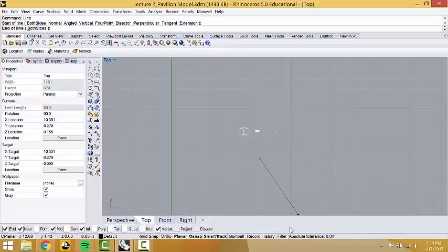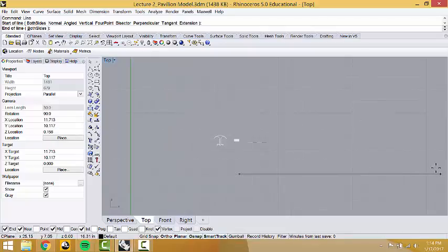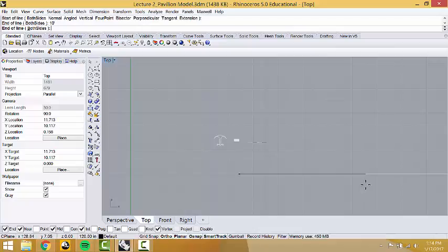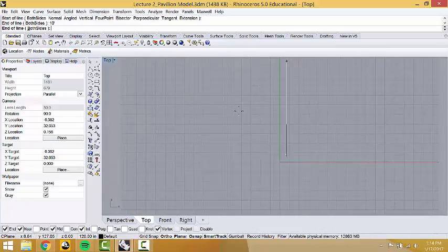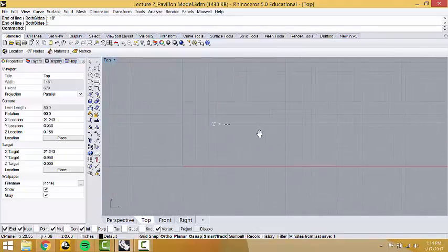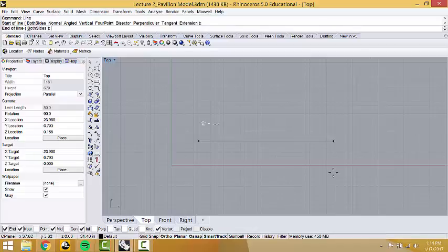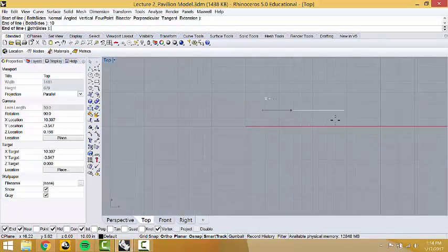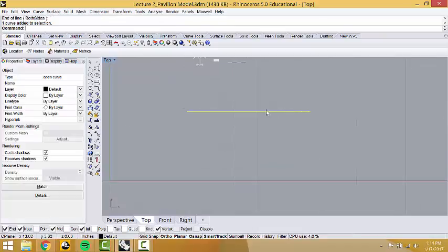Some of you guys, of course, already know this, but if you ever want your line to go straight to the side, you can hold shift and it will only move orthogonally. But if you are always drawing only perpendicular or straight, then click on your ortho and type 10 feet, enter. The command is not complete yet. When you hit enter, you have to enter again. Oh, I know. You have to click it again. So click 10 feet, enter, and then click, not enter.